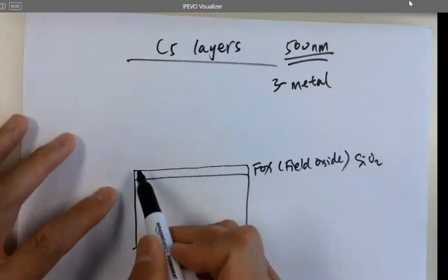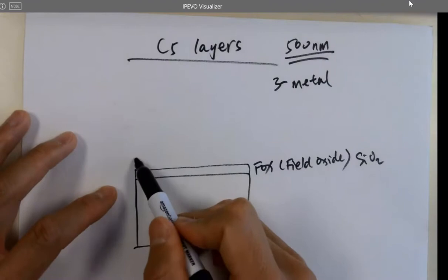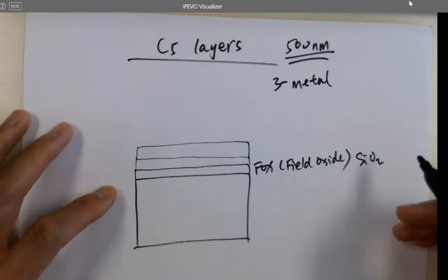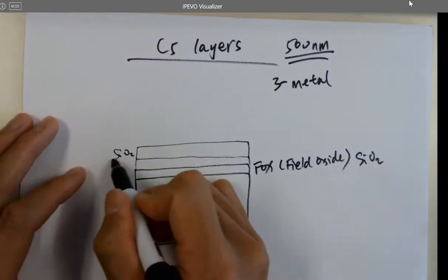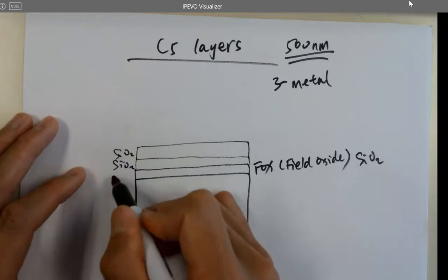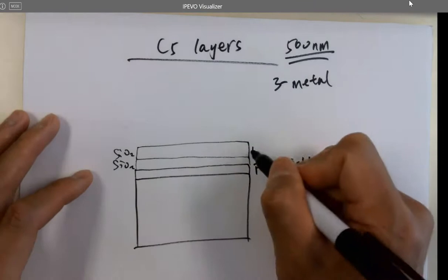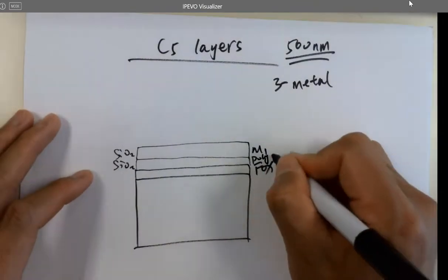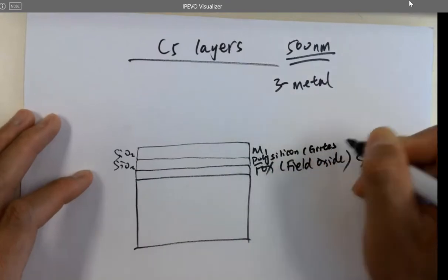So if there's only a metal line, with nothing underneath it, just a metal one. So these are all silicon dioxide layers, right? Same. So metal 1 is over here. And here's called polysilicon. It's for the gates or capacitors.